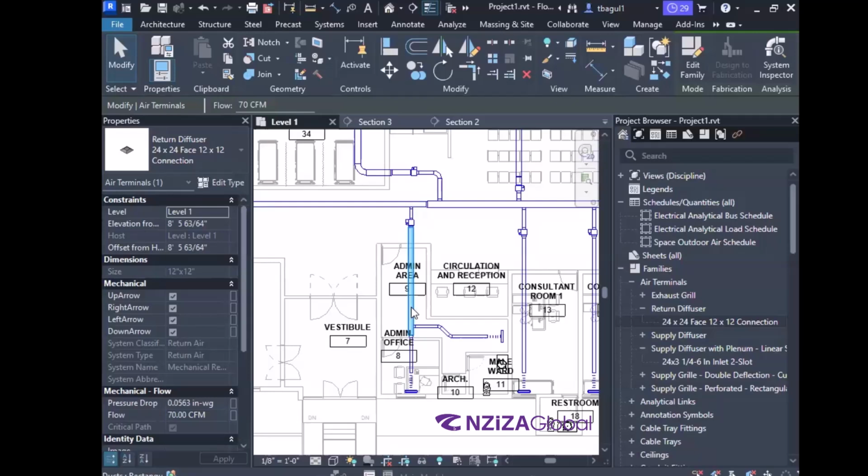Right. Okay. So for the folks online, the question in the room was, what if the CFM in the operating theater reduces as compared to the CFM in the corridor? In that case, we will have a corridor positive pressure as compared to the operating room. The operating room becomes negative pressure. The air will start flowing into the patient, into the surgery room, into the operating room, which is not allowed, right?